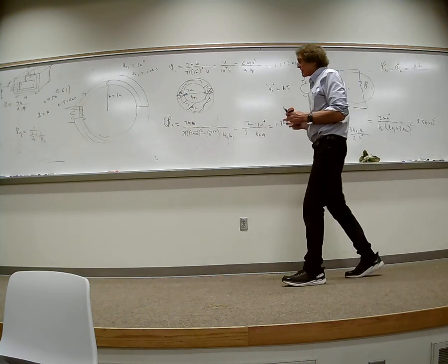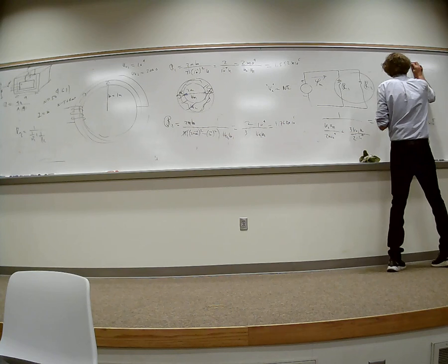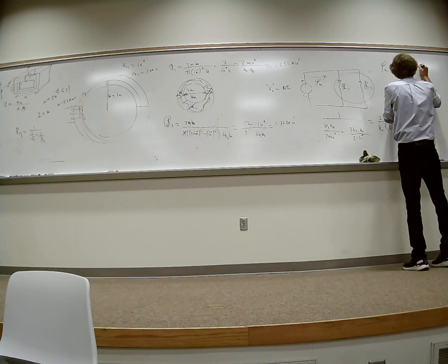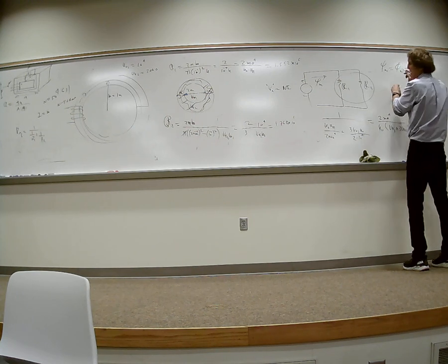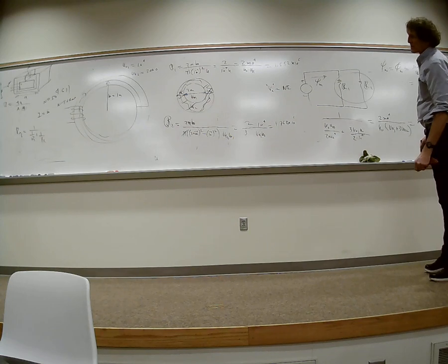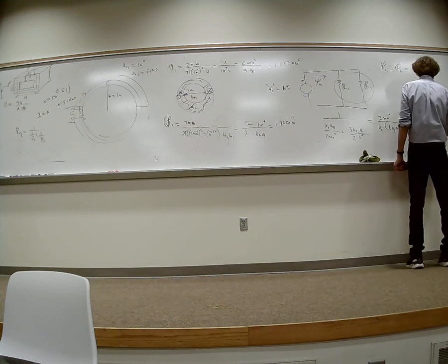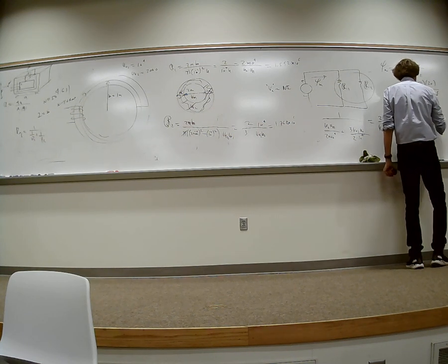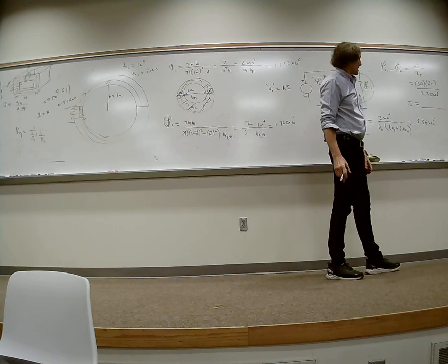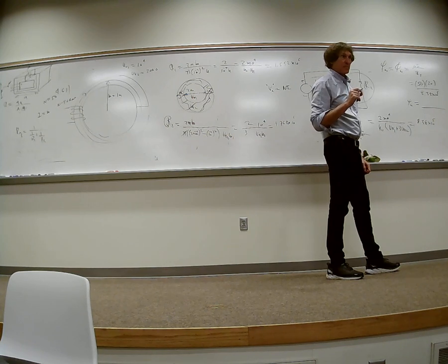If we have that, now here's the reason I'm doing it. Next, I'm going to get the total flux here. So I'll take Ni, right here, divided by the reluctance total, equivalent. So N is 50, I is 20. So I have 50 times 20 over the total reluctance, 8.38 times 10 to the 5th. Now, what is that value of magnetic flux? I'll tell you what I'm doing. I'm going to show you something here. You can get the inductance for this in a direct way. This is important to see.